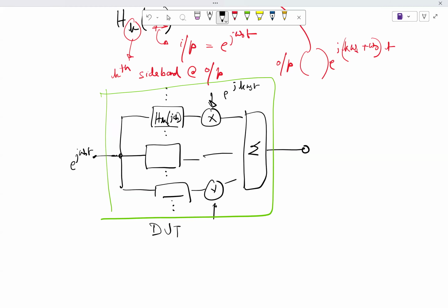So now when you have that input, you put it in a spectrum analyzer and you are looking for that impulse and you are finding out the value. Experimentally, what does it mean? You are putting a band pass filter around the frequency of interest, and the power at the output of the band pass filter is conveying the strength of the transfer function, correct? So the key thing to take away is that we need to put a band pass filter around the frequency at which I'm interested, correct?